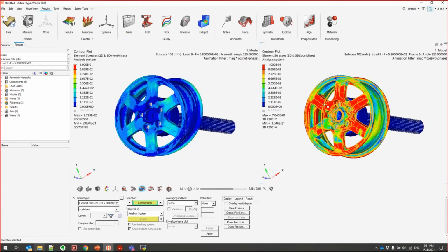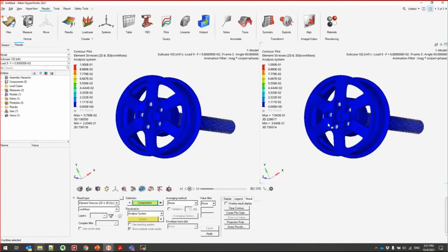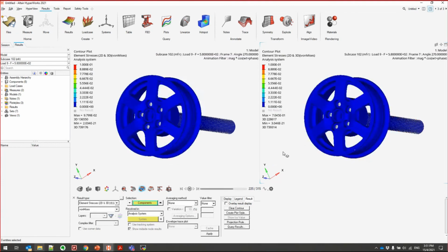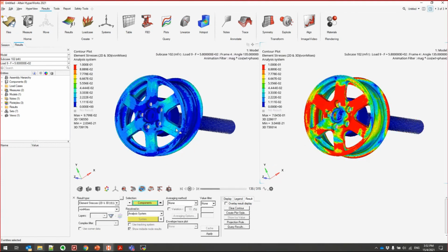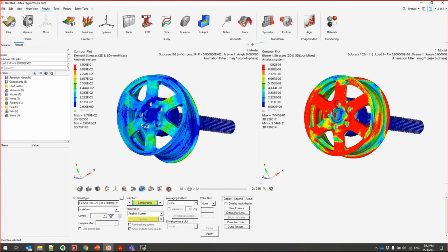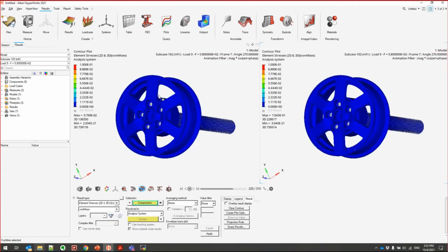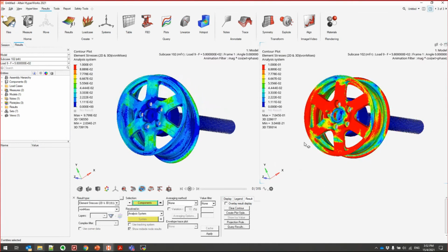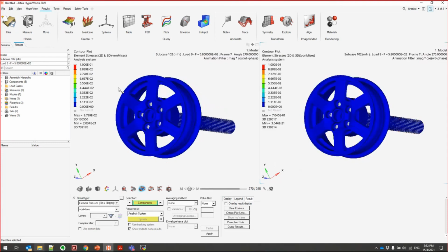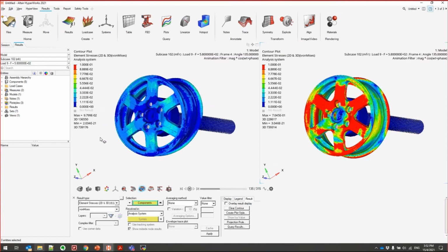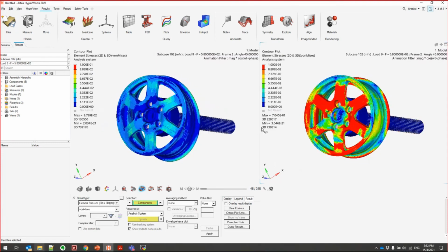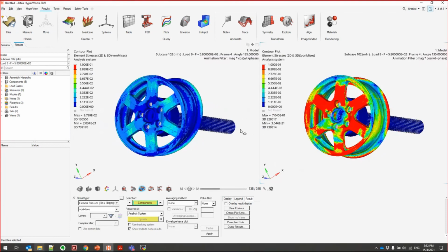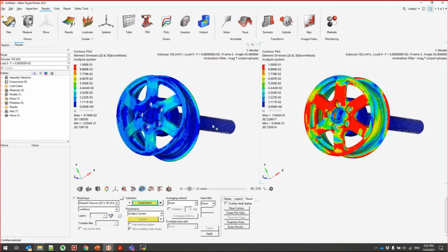Yeah, so the stress you see here is higher because it's being pretensioned. With higher stiffness, of course, you get to see higher stress, right? Here it is still free to vibrate. So you see here it's like a loose connection, but here is a really tight connection. So you definitely get different results if you pretension your model or not.